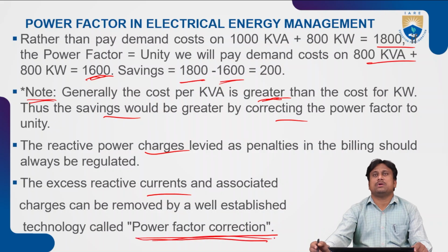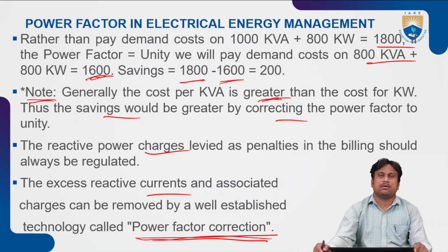If you are not making suitable power factor correction, your authority may have to face the charges, and that should directly or indirectly fall on the customers. So they will suffer more in electricity bills. To come across that, we should implement power factor improving devices like capacitor banks across the lines, improving the distribution system efficiency, and adopting new technologies to correct the power factor.